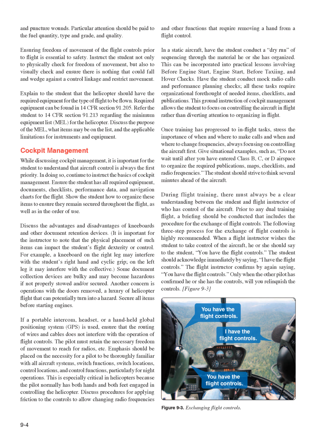Cockpit management. While discussing cockpit management, it is important for the student to understand that aircraft control is always the first priority. In doing so, continue to instruct the basics of cockpit management. Ensure the student has all required equipment, documents, checklists, performance data, and navigation charts for the flight. Show the student how to organize these items to ensure they remain secured throughout the flight, as well as in the order of use. Discuss the advantages and disadvantages of kneeboards and other document retention devices.